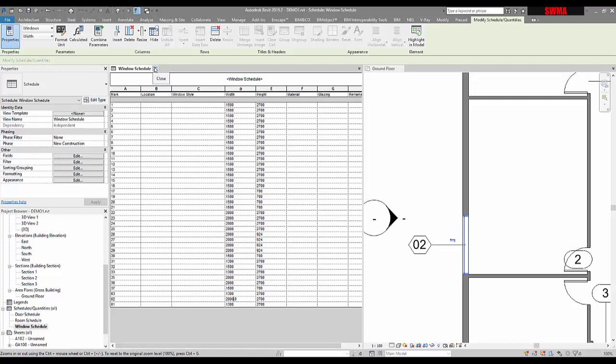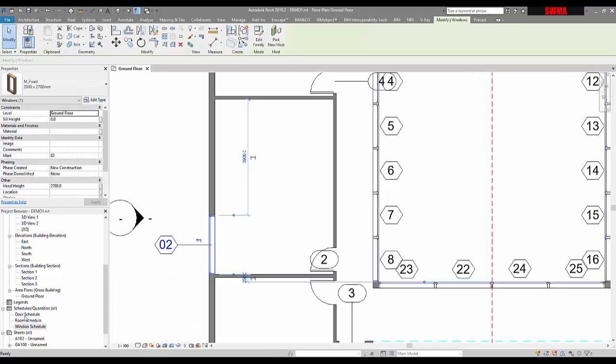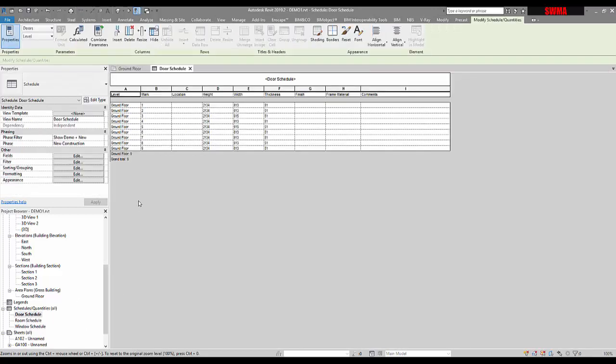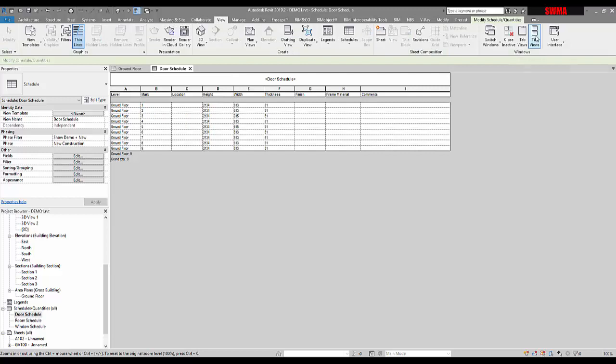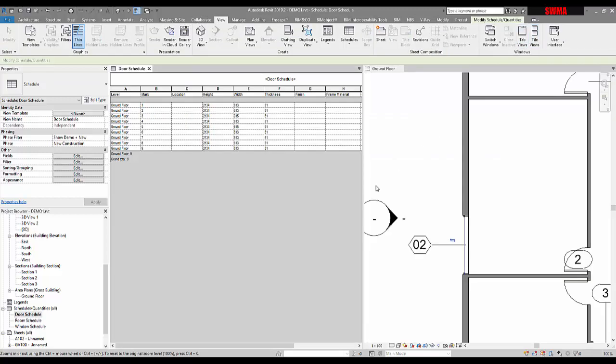There's also the heights and the widths. So if I go and bring up my door schedule, and let's say all the doors, so again I'm just going to go back here to tile views. WT is the shortcut tool for that, so WT. I want to now go to these doors, and maybe I want to drive some of the parameters here.